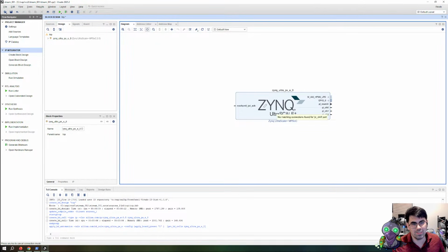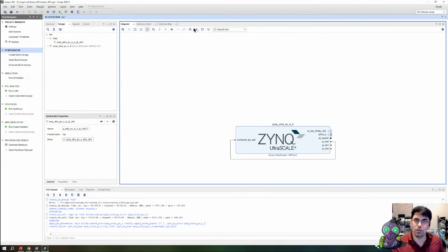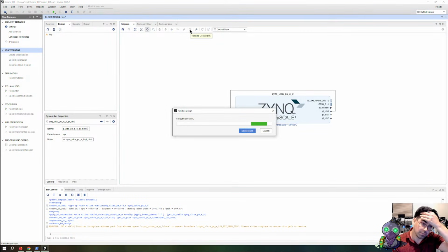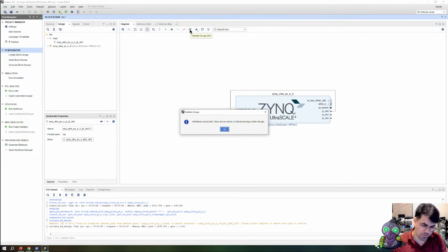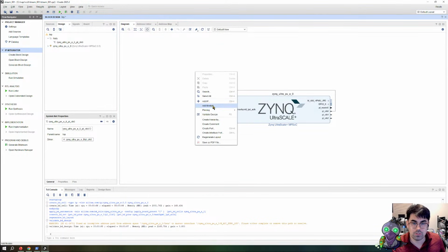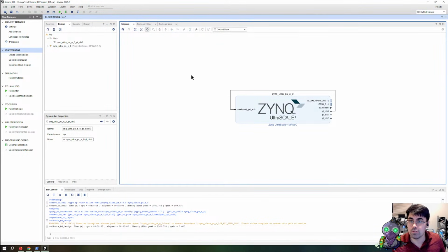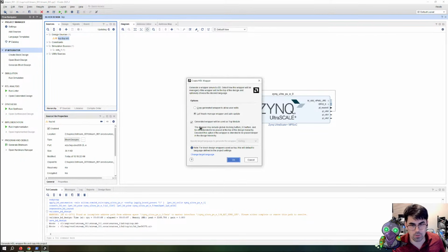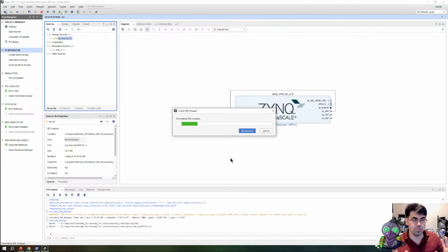To get a complete diagram, we're just going to connect the clocks up, and then we'll be able to export this to Vitis. We're just going to export the hard processors right now to Vitis, and while Vitis is building, we can come back and add a soft processor. So we validate it, we save it. We're going to go to design sources. We're going to create an HDL wrapper. We're doing the default settings. Let Vivado handle any changes.